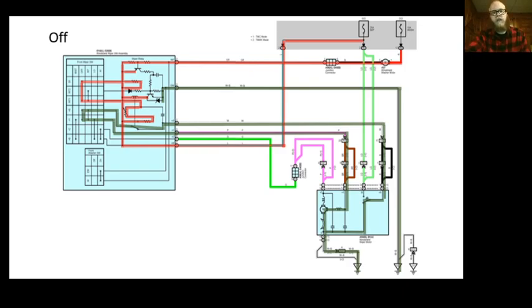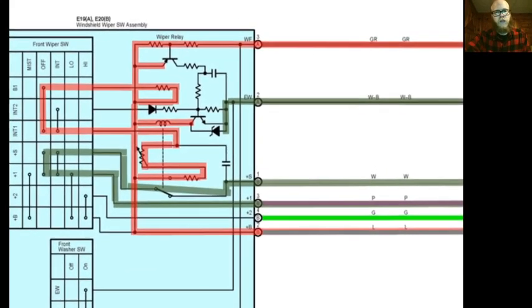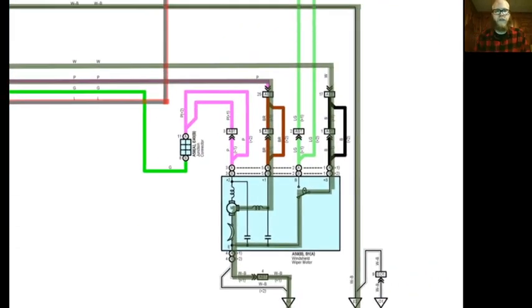And down here, well, let's zoom in here first. This switch setup is different. This is more of an Asian style diagram, being Toyota. And all this means is when I'm off, I'm connecting this circuit, see the little circle, with this circuit right here. Or this circuit with this one. Okay, so they're just showing that the switch connects these wires together, which is what switches do. They connect wires together. So what's happening, we'll go down here, is I've just supplied ground to my motor.